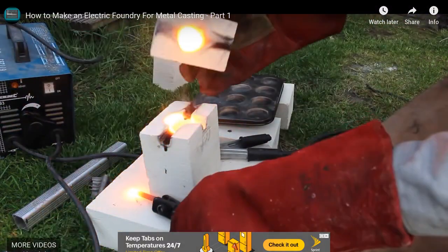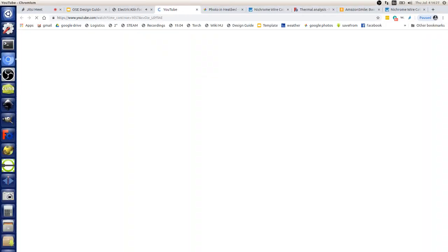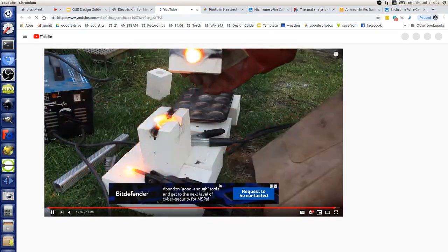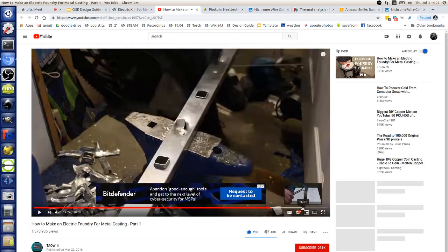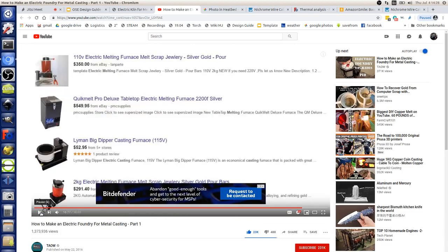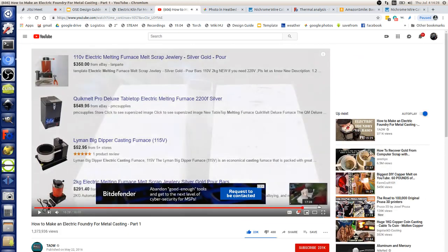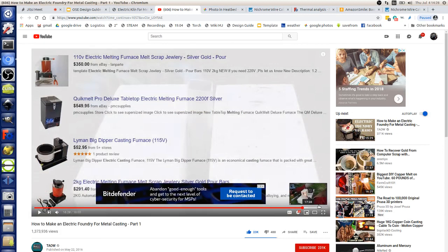But the relevance to the Global Village Construction Set and 3D printing in particular is that using a simple surface furnace like this, we can be doing lost PLA casting. So you can 3D print an object, cast plaster of Paris around it, and burn that shape out, or just use special filament.